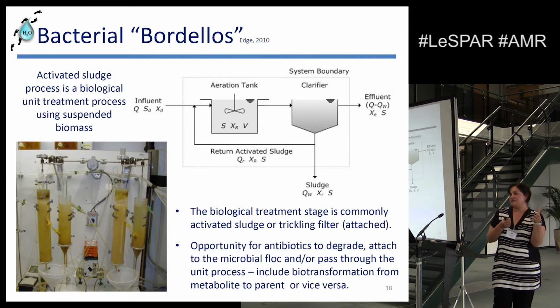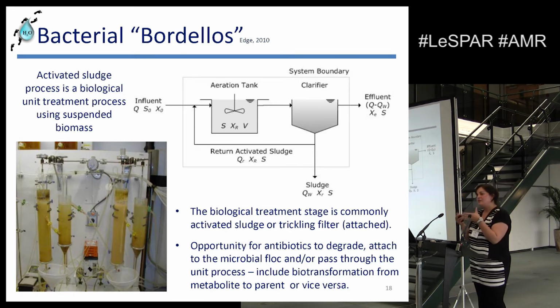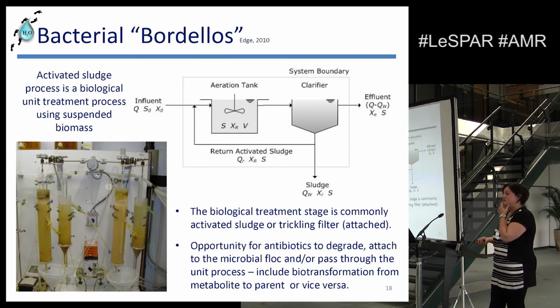After primary sedimentation, you then put it into a system where there's a lot of microorganisms, and there's so much you can actually see the flocks. And that allows them to then use the wastewater as a nutrient, as a food source. So it's removing the pollutants because it's acting as its food source. And then you clarify it out. So it is a biological process.